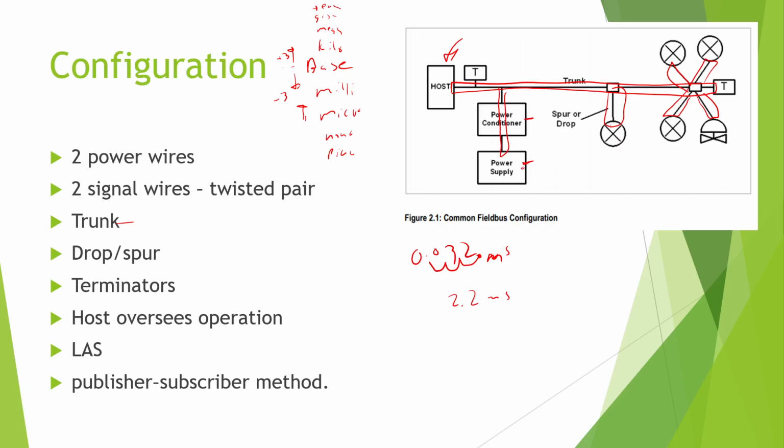What we're also talking about here with the cyclic and acyclic is things reporting information. A sensor could be reporting some information consistently: every 1 second or half a second, whatever my time is, I'm reporting information. That would be cyclic. Whereas maybe you have a VFD where it's like, I am sending you information, you're responding to me. That would be acyclic. It's not always going to be transferring information. And then lastly, we've got a publish and a subscribe method. What do you think that means?